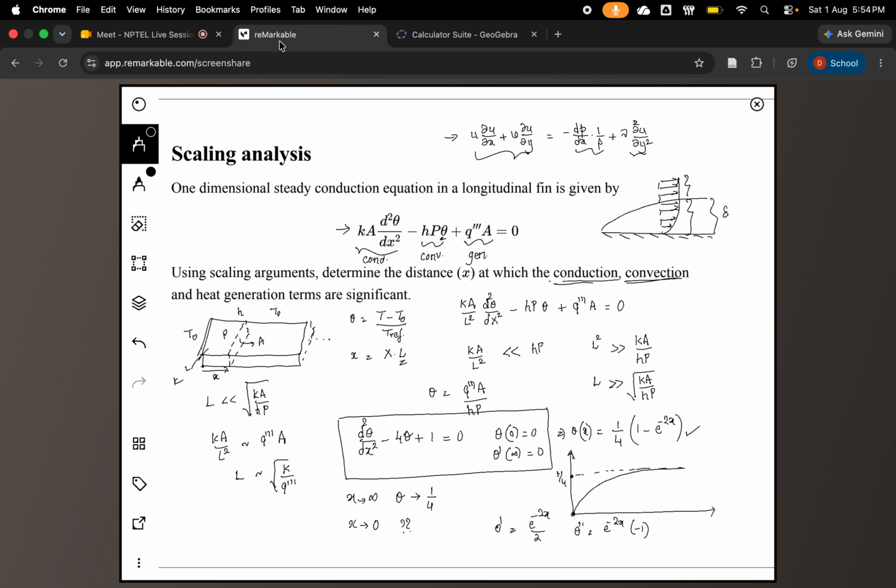and then the equation will reduce to a form which can be solved in some simpler way than solving the overall equations. Like when we start with the Navier-Stokes equations, which are very difficult to solve. So we understand that there is this scaling behavior where the relative strengths of each of the terms are different in different regions. So we will split the entire domain into different regions, simplify the terms accordingly in each region, solve the solutions in each of these regions separately, and then see how to match them across these different regions.